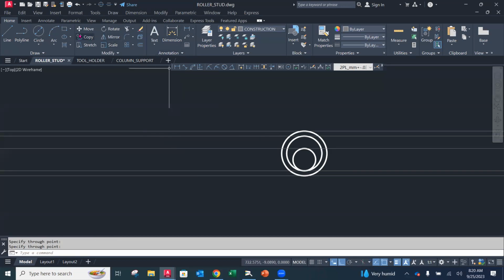Okay. So now we are going to do a line. I'm going to go about here. Here we go. And that's just a construction line. I didn't use the official X line, I just drew a line going vertical. Either way works. And now I'm going to do offset, and I'm going to offset my distances back.